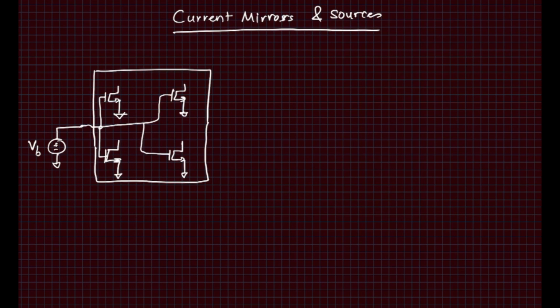Also, there is something called a ground connection. This ground connection may be going to different locations on the chip, and there could be different resistance in that path. If there is any IR drop in that ground path, then the amount of current will also change in each case. This is not a very desirable situation. So don't do this. This is not a good way to bias your transistors and create current sources.